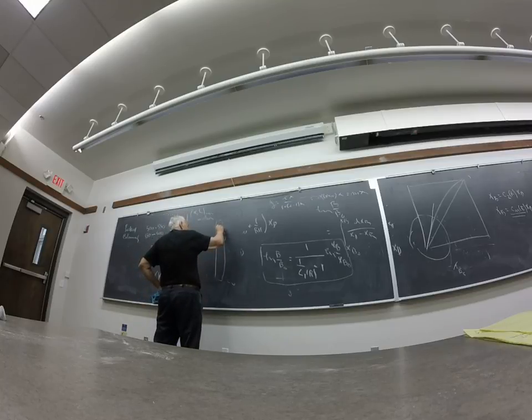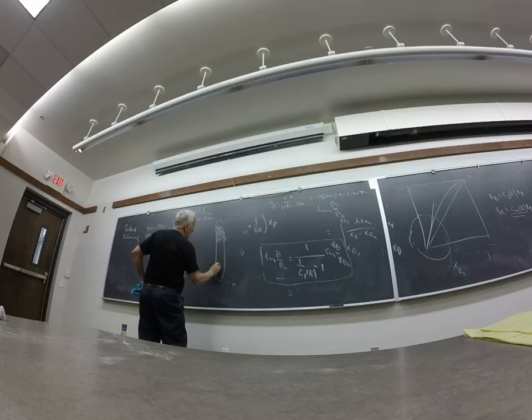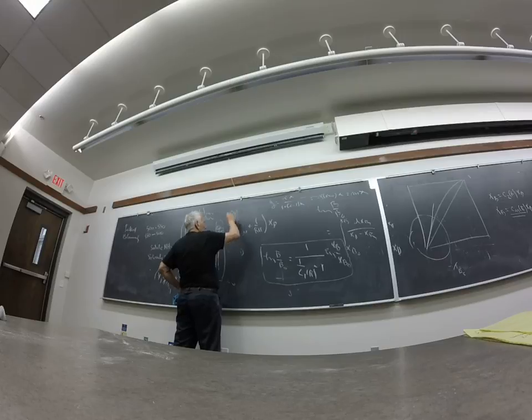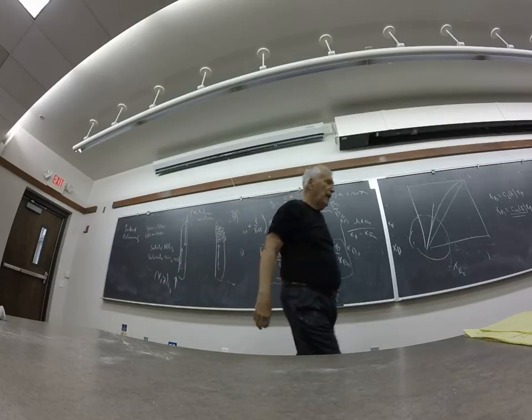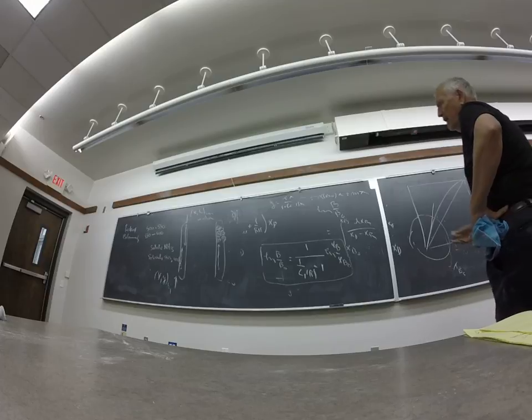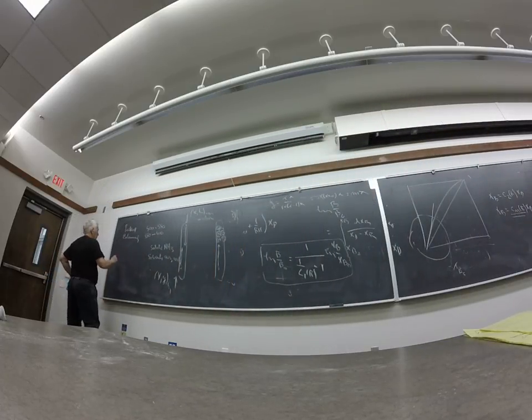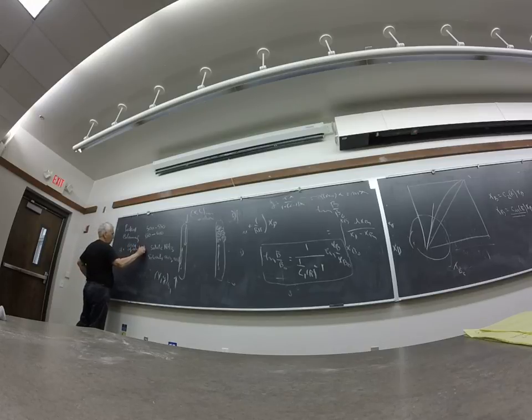Then the liquid trickles down over the packing, and the air is blowing up through here, and so you've got a piece of packing here with a liquid film on it. You've got air flowing past, they're exchanging mass, and we will probably introduce a notation that says something like A equals the area of contact per unit volume of the column.